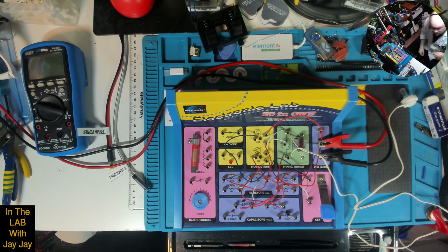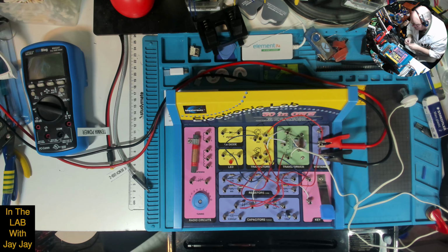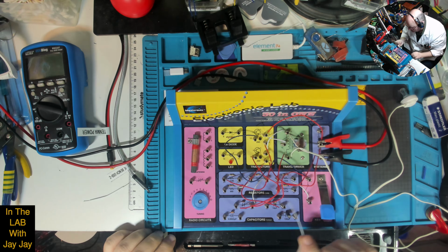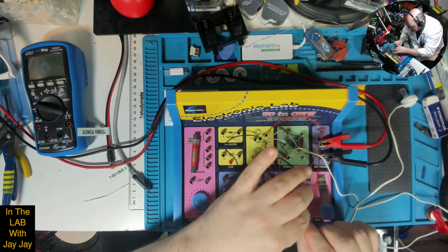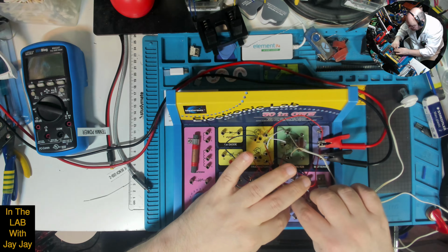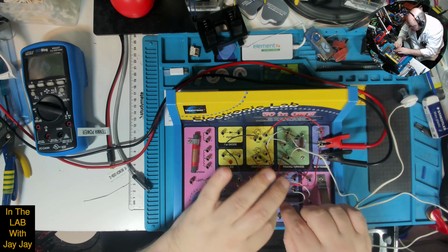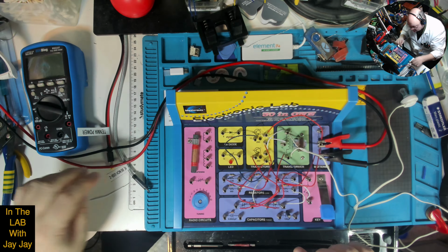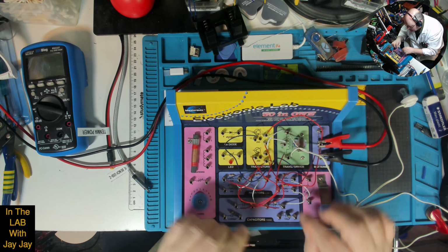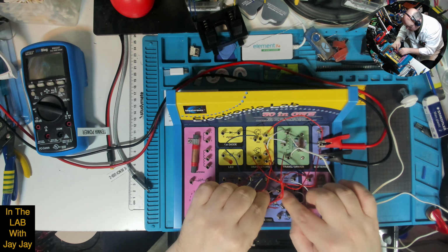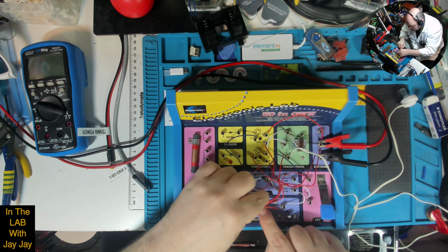So we just need 2 white cables, which we've got. So we'll just connect the 470k across the capacitor. This will discharge the capacitor, and it should help us have an oscillating tone when we press and depress the button.